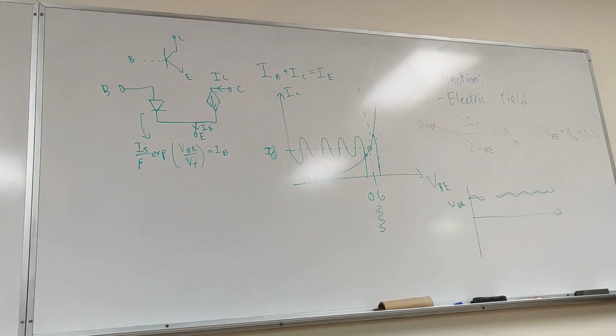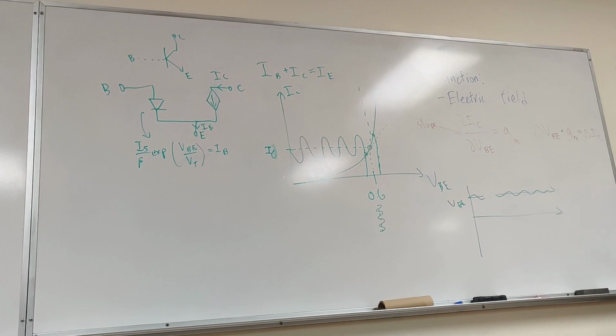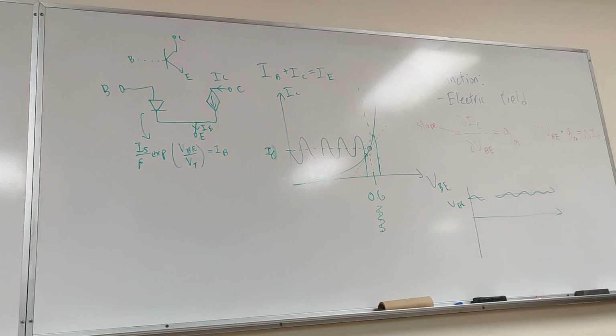So now the general idea is, we pick an operating point, a point where our BJT is in the forward active region, and now we apply a certain sinusoid to it. The reason is that in RF, we deal a lot with frequency. We want to apply sinusoids, amplify them, send them to an antenna, send them out into space, receive them. So this is very useful, because now if we apply a sinusoid to the input of our amplifier, what happens to it? Same idea here. So now we have a certain notion of gain. We apply a certain voltage, get a certain IC, and this gets converted through this factor called transconductance.